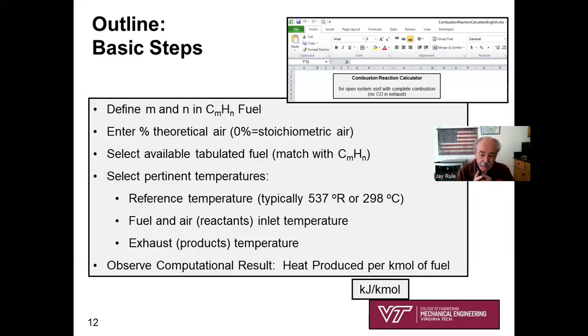And what's the objective? The objective is to go through that first law of thermodynamics, an accounting nightmare, and determine the computational result, which is the heat produced per kilomole of fuel. In other words, little q bar. The result will be kilojoules per kilomole or BTUs per pound mole.